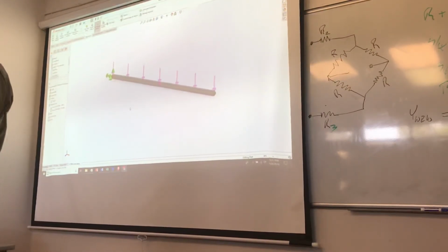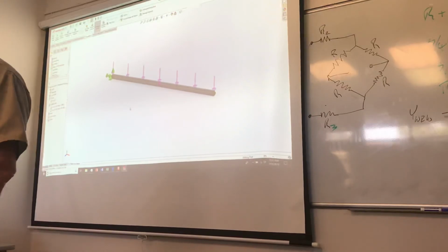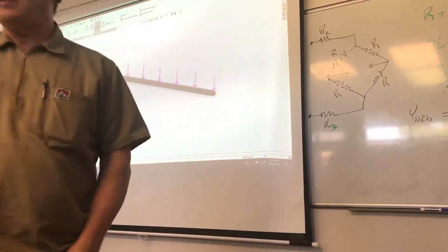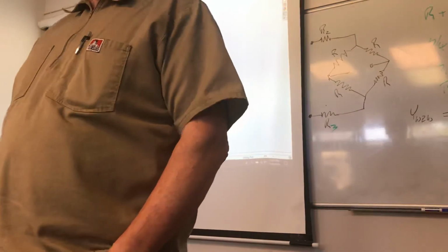But then you can copy them, and you need to copy them into somewhere under Program Files, SolidWorks, then the language, English, weldment profiles. Which is a long way to get there, but you'll eventually figure it out. That's the hardest thing to remember, where they put the darn things, because they hide them so well. They don't tell you where they are.